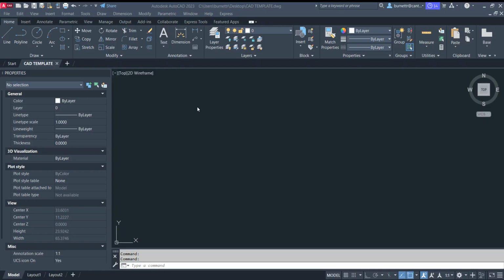We're going to be covering lab number 4 today, formatting a CAD template from scratch. The goal with a template is to ensure that every time you start a new drawing, you already have all your settings built in: your layers, the layer setups, names, colors, the annotation styles, so text, dimensions, multi-leaders, and units. Companies often do this so that all of the employees start with the same set of standards, and it just simplifies things, keeps everybody working on the same page.